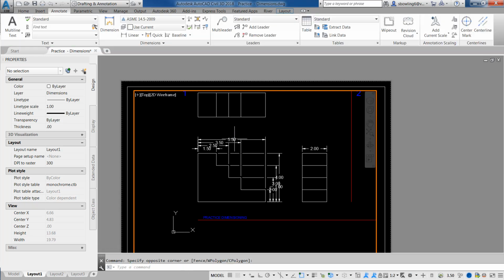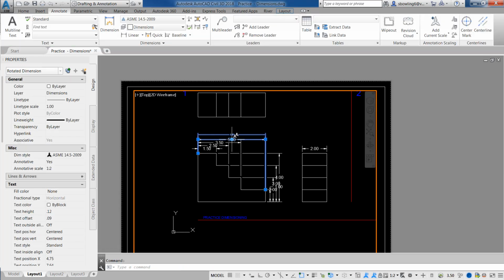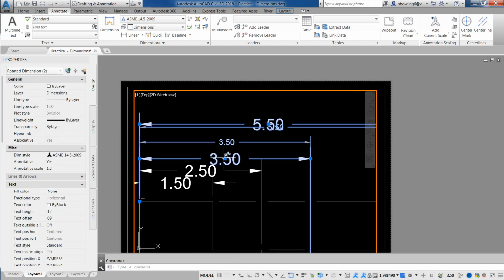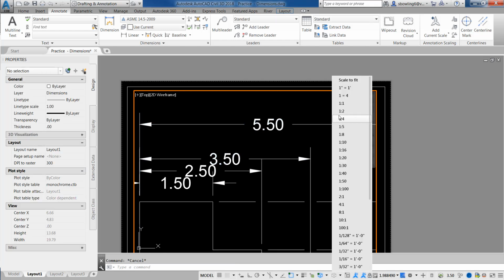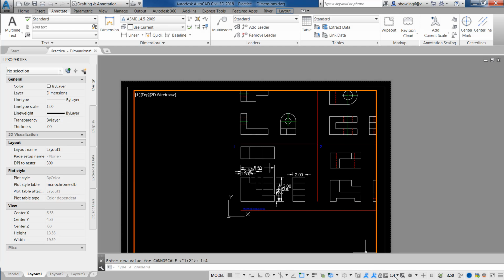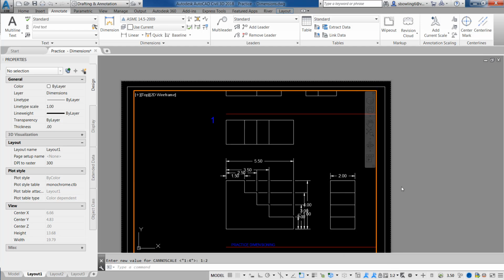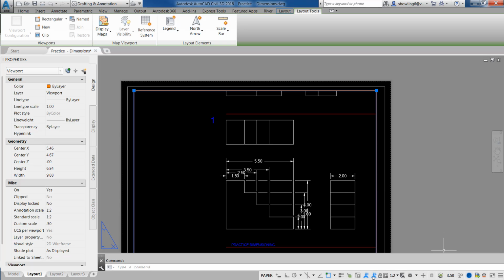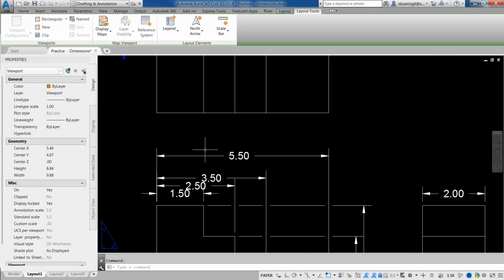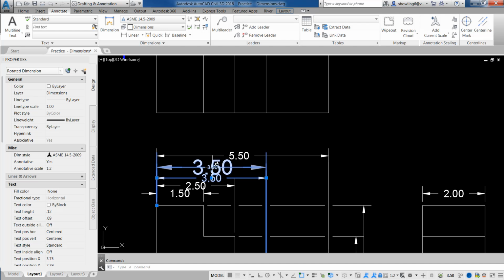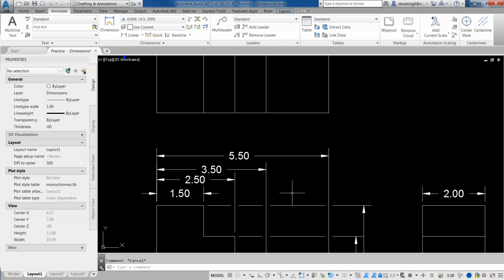Sometimes you could do it through the viewport. See how you can see doubles? Pull it up. I always like to hold the scale 1 to 4, snap, 1 to 2, double click. I'm going to lock this. So what allows me, I double click on the inside, and this is why I don't like annotative, because it gives me 2 of them.